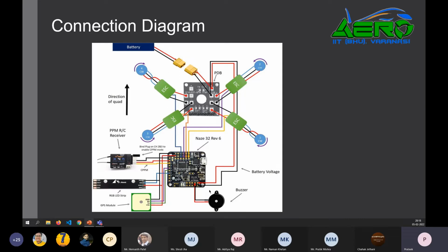You can program your own flight controller, but that's going to be a little tough. You can code your own PID functions into them. But mostly people use ready-made flight controllers and load different firmwares that already have everything coded into them. You just need to assemble everything together and it's ready to go. Another option is you can make the flight controller and receiver on your own, and buy everything else.